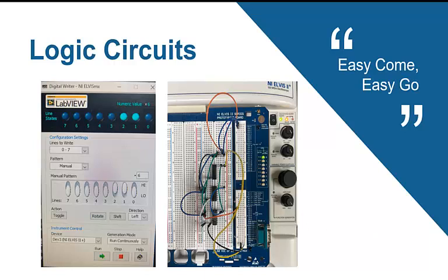Note that when you are going to connect the ICs on the Elvis kit, we have here VCC is 5 volt, and all of 14 leg of these 3 ICs will be connected to 5 volt, and all of the ground will be connected to the same line here, which is ground. And here DIO 0, 1, and 2 will be considered as A, B, and C as inputs.